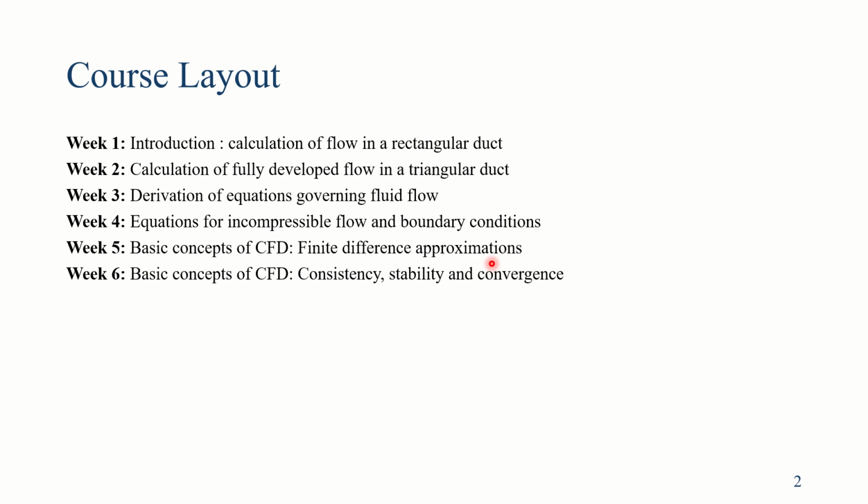When we are solving the equations through any numerical method, we need to have an idea that we would be getting the solution converged. Sometimes solutions might be diverging, or might not be stable. There would be many errors and fluctuations, and we do not want that. Therefore we need to have some checks periodically from the equations that say we can have consistent, stable and convergent solutions. For that we also saw Lax's theorem and how it states the convergence theory.